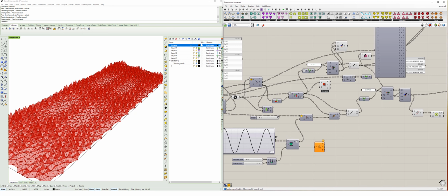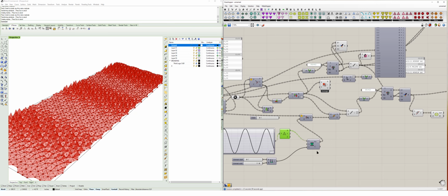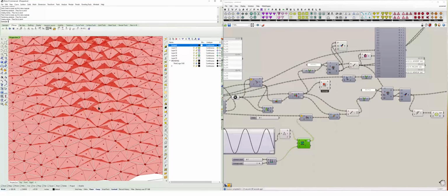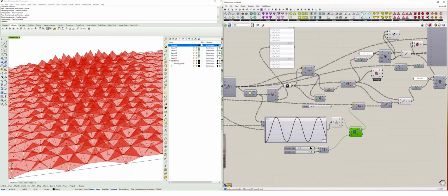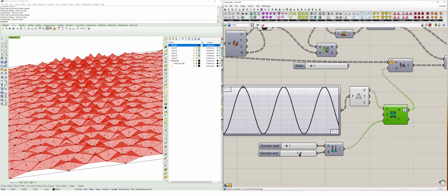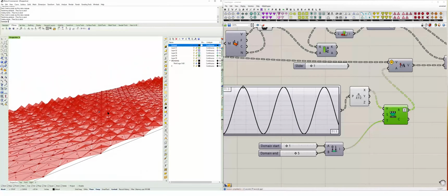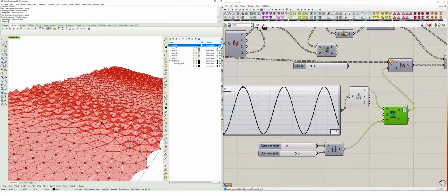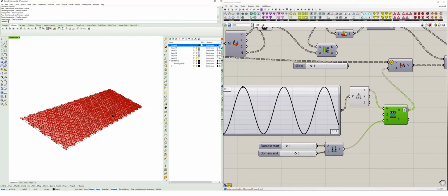So plugging in my graph output to deconstruct point, and then only taking the X value from that and remapping it is going to give me one direction. And that's going to help control my input here. And likewise, we could reduce this height to be a maximum of something less if we want to, depending on what proportions we want. So in this case, we have a maximum of 6 inches here, a minimum of 1 inch offset, and that's undulating based off of the sine curve here.